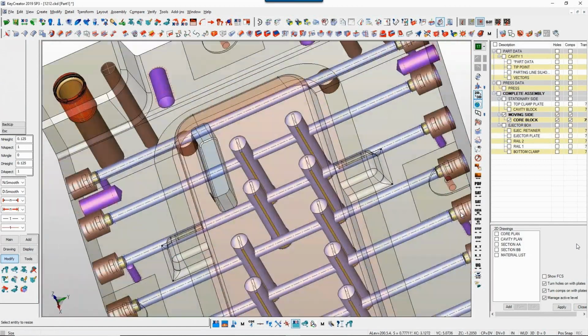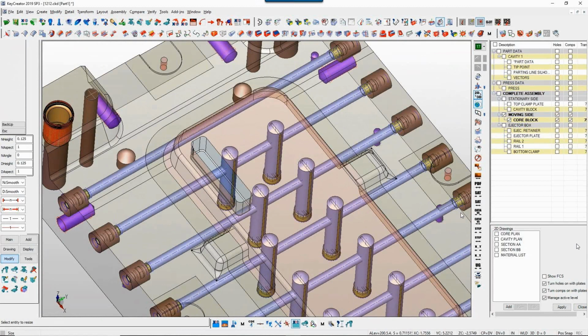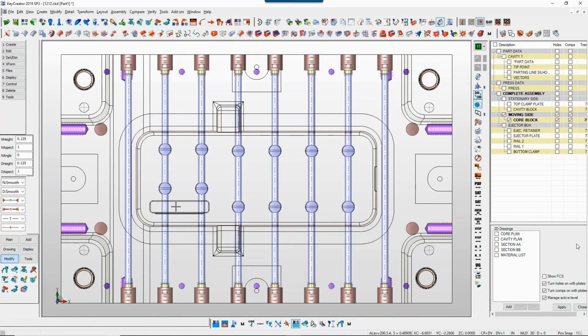So I'm never, ever calculating my actual baffle heights. I'm just telling it how far I'm OK with it being from certain features. Okay? So when you get close to these pockets and stuff, you can put in whatever value you need to make it work. If you need to get up inside a tower or anything like that, but I don't want to be any closer than a couple hundred thou away from the sidewalls, you can tell it that.